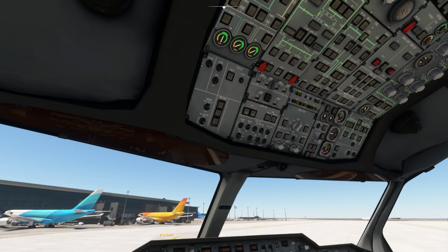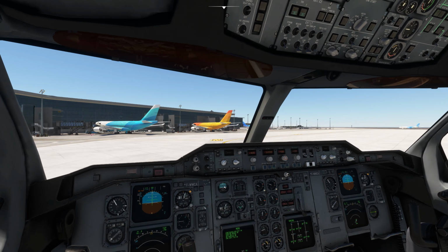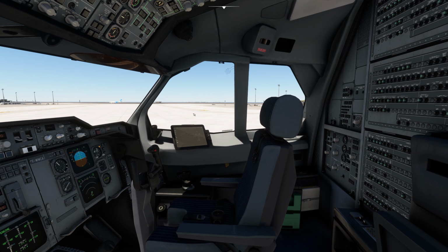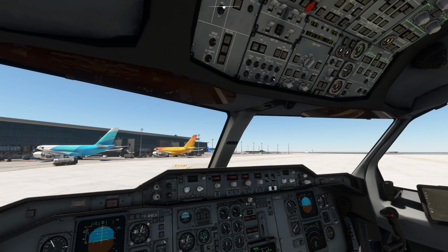And turn on the lights, runway turn off lights. Basically these are the lights on the left and right hand side of the plane, which enable the pilots to see at night. In the morning we turn them on so that planes at a distance, if they are unable to look at your plane, these lights are so bright that planes at a distance can easily see your plane. Just turn it on. Wing light, just turn it on. Landing lights, set them to off, and nose, set it to taxi, and before the takeoff I will set them to on. That's it.